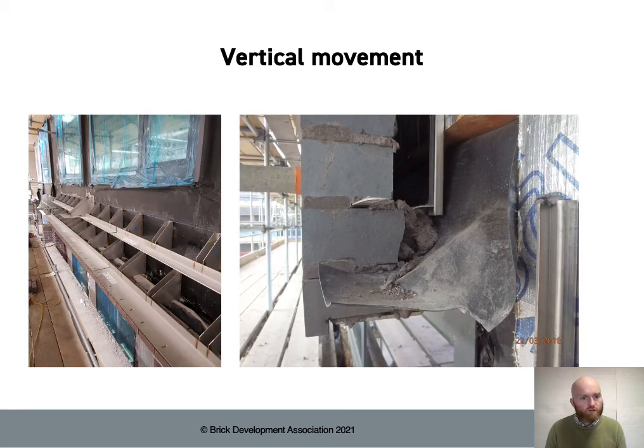Just a couple of photos of what that looks like in practice. You can see on the image on the left quite a complex detail with clearly some stepping masonry, some stepping support angles there. This image on the right, there's a few issues with mortar being dropped into the cavity, and that cavity tray should extend for the full width of the bed joint, but you can see that masonry support angle in there underneath.